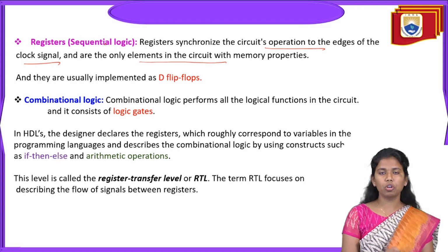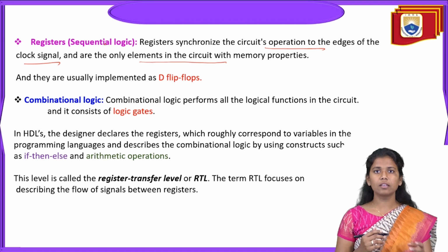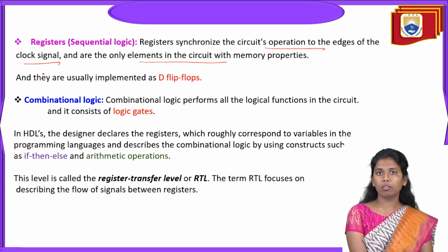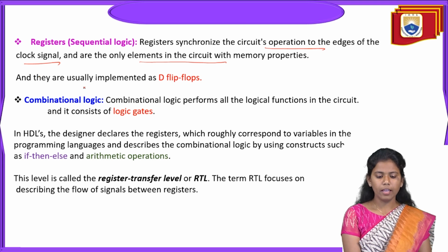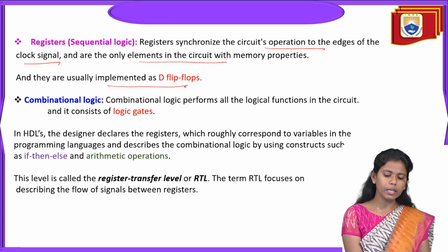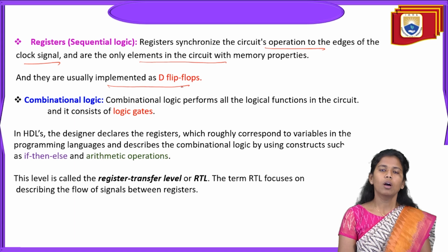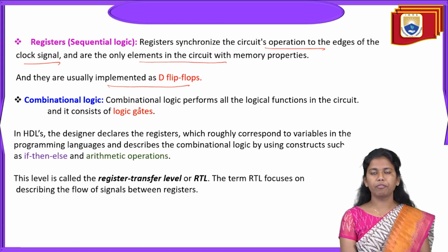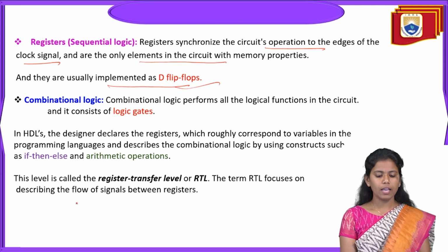So in the sequential logic, as we are considering the registers as the basic building blocks, we come across a clock signal, and they are usually implemented as D flip-flops. Prominently we go with D flip-flops compared with SR flip-flops, master-slave flip-flops and T flip-flops. Maximum times we are using D flip-flops.